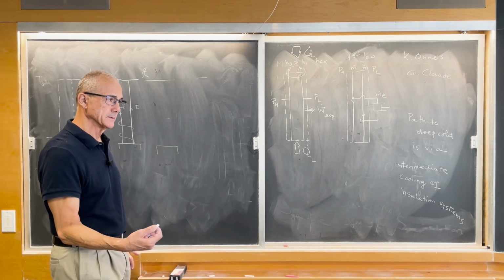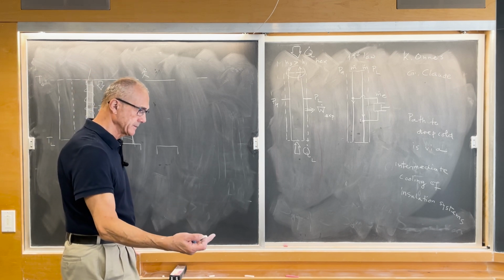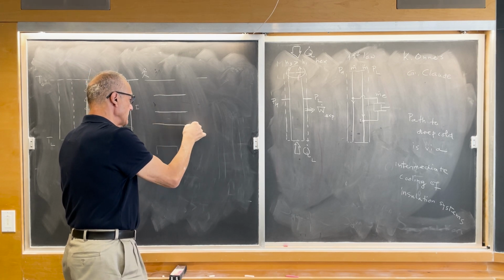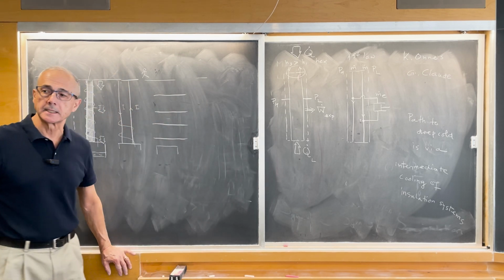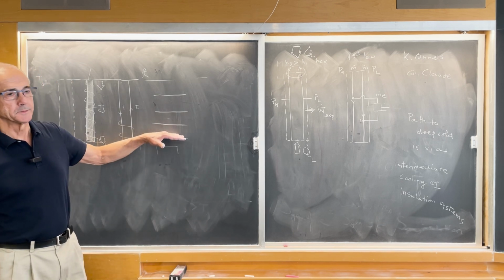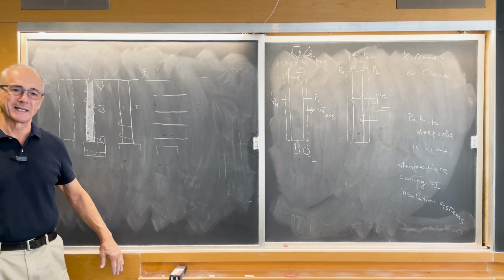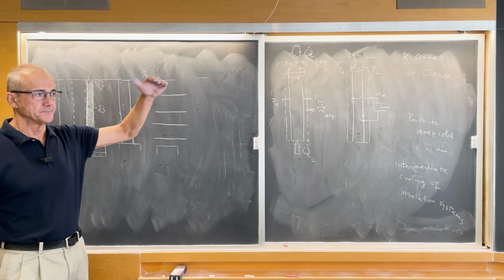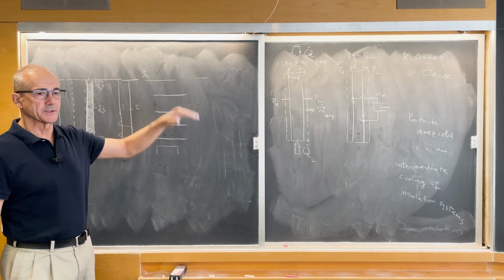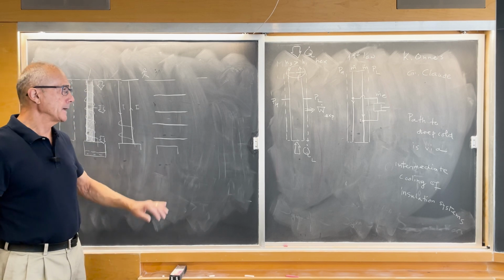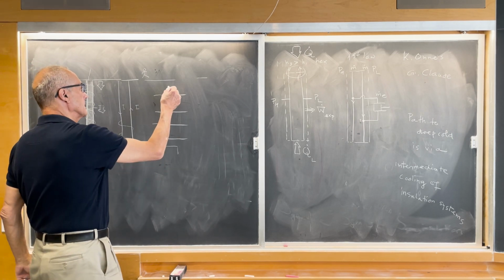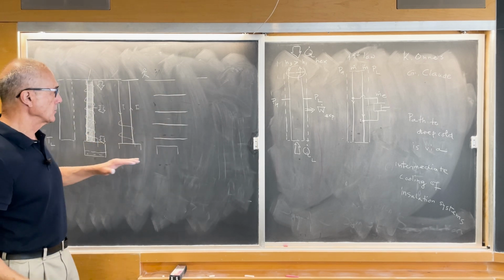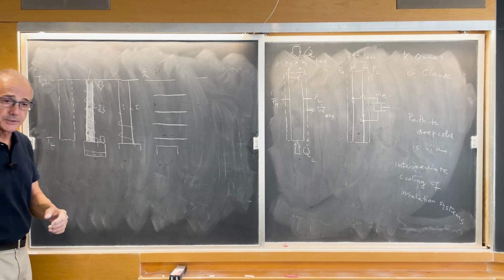The meat and bones of the technique is radiation shielding, installing concentric, let's think of them as blades, thin, like one ceiling succeeded by another. Radiation shielding is the equivalent of what you see here for conduction.